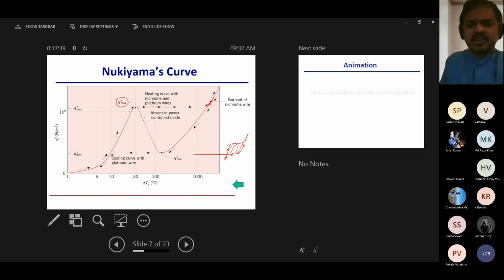It has to do with surface energy, but if there's a film and you don't allow enough temperature difference, the film just suddenly breaks up into smaller bubbles, and they escape from the surface. And as they escape, they take away a lot of heat and suddenly the temperature goes down. That is exactly what happens in this part.